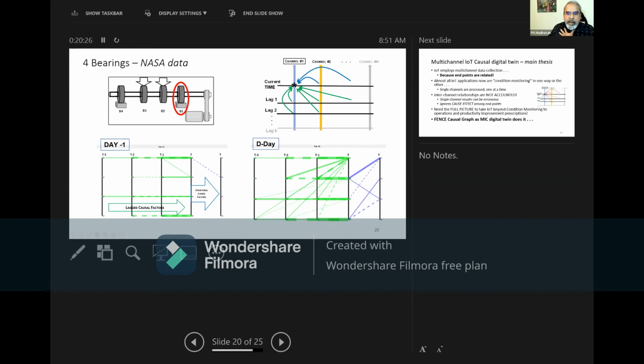Their interrelationships are all causal factors. How much of the data from the previous sample is causing the current data? How much of the other bearings' vibration is causing this B1's vibration, the bearing that fails, and so on. So the algorithm determines all these causal factors. It is fairly complex, but it's been done. And the reason I'm here is that I'm going to open source all of the algorithms and details. The result is just stunning, and again, very easy to see.